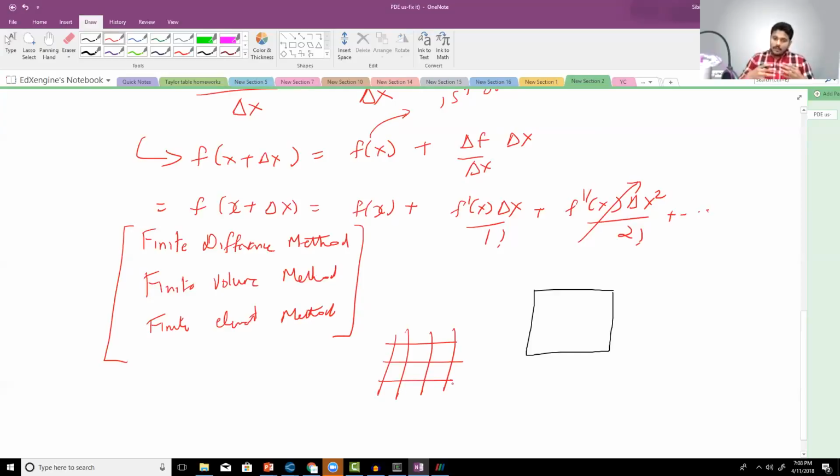Whereas in finite volume method, you are basically discretizing what you call the integral form of the governing equation, which is derived for an entire volume. And the shape of the volume is not taken into account at all. So it can be used for any shape. Similarly, finite element method is based upon shape functions. It can absolutely be used for CFD. The reason why you don't use it for CFD is because at the end, the linear system you solve becomes much larger than what you get with FVM methods. So it is not efficient.